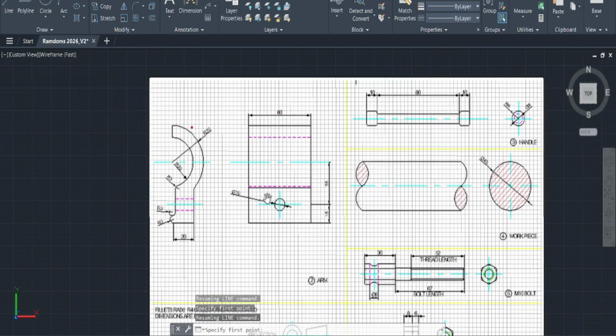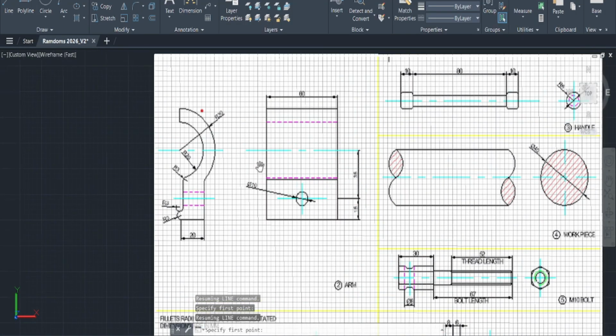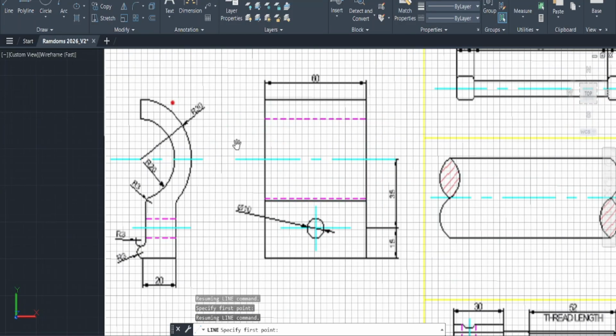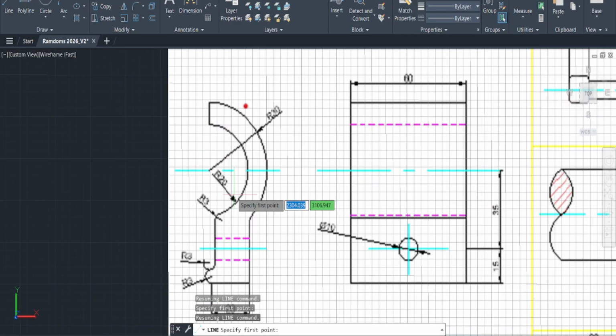Because I would have set up the horizontal for the 15 and then the 35 here respectively, the next thing I want to do is get the total height of the object. And from what I'm looking at, the total height of the object depends on this particular semicircle construct, where the inner one is actually R20 and the outer one seems to be R30.